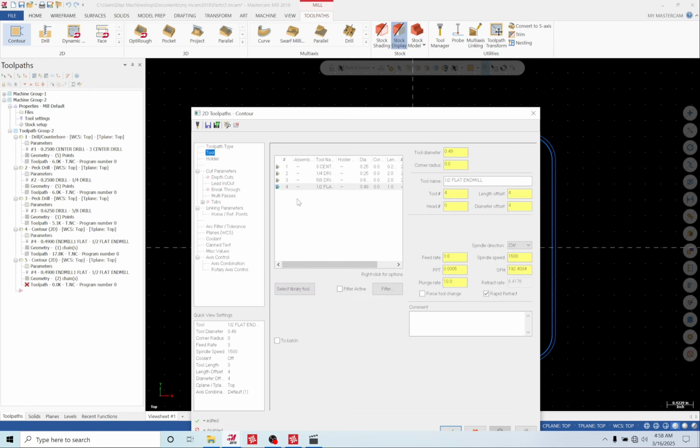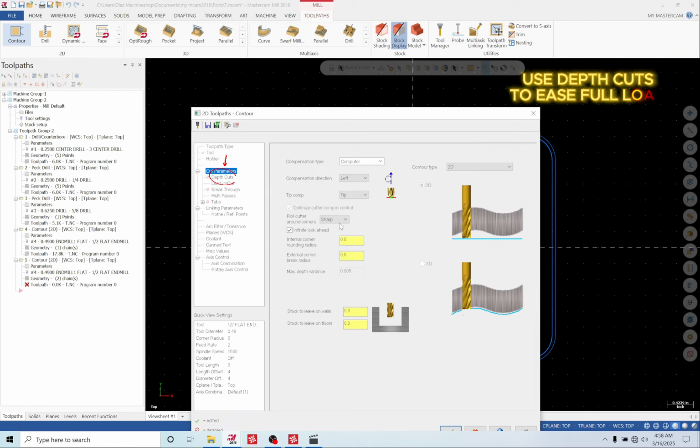so we would go to tool, select the end mill again with similar settings on the spindle speed and the feed, just to go ahead and rough out the center slot.